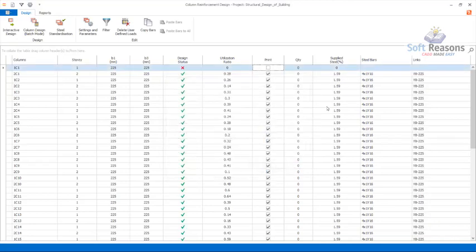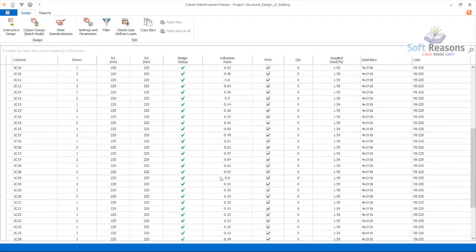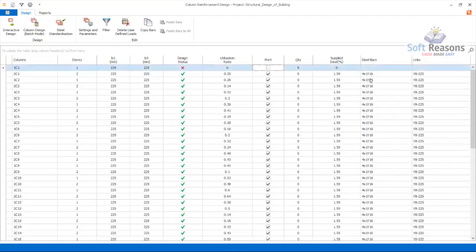So click on close. You can now see all of these bars, the concrete column has been designed successfully. And then you see the U ratio is very encouraging. Very encouraging U ratio that we're having. So all through is 4Y16 diameter reinforcement, and then we have the links expressed as 2 to 5.